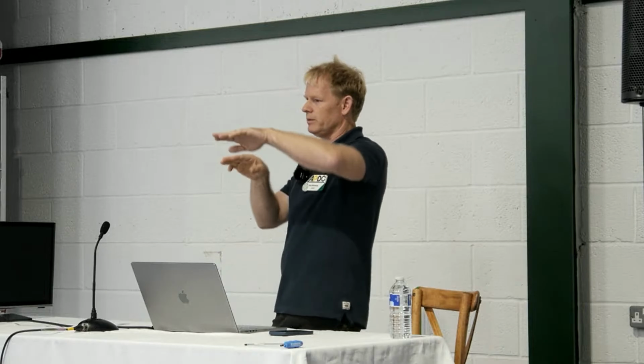And it turns out, because it's a spinning system, if you apply the force here, it doesn't tilt up there, it tilts up or down half a cycle later. So there's a phase lag between where the blade flaps up and down and where the force is applied. And the size of that phase lag is controlled by the distance of the hinge. And that's something that these BM models have to model.